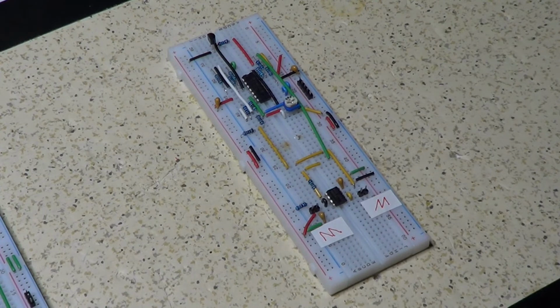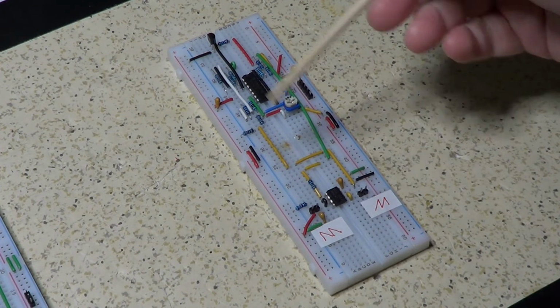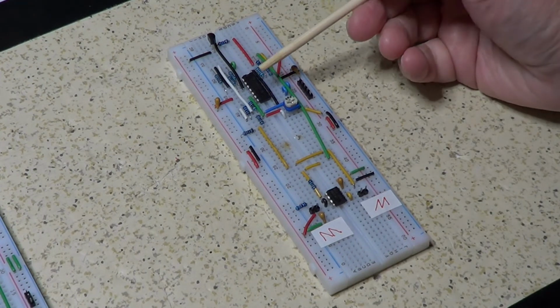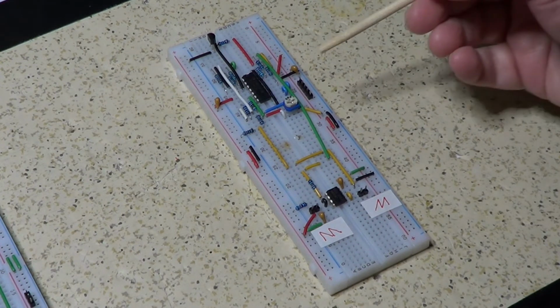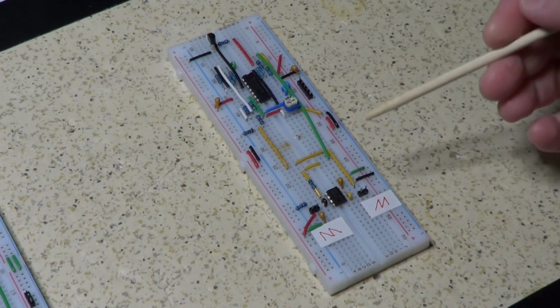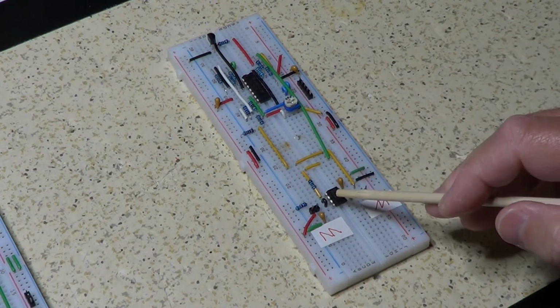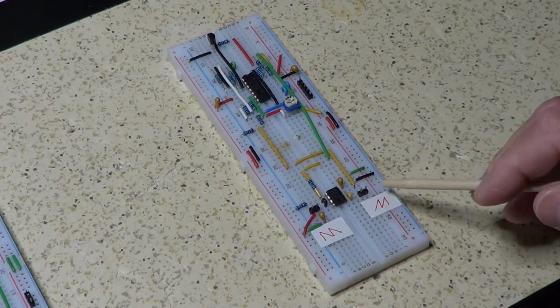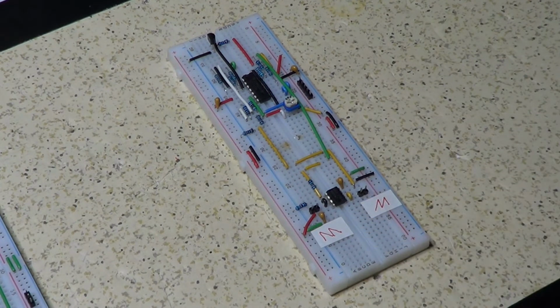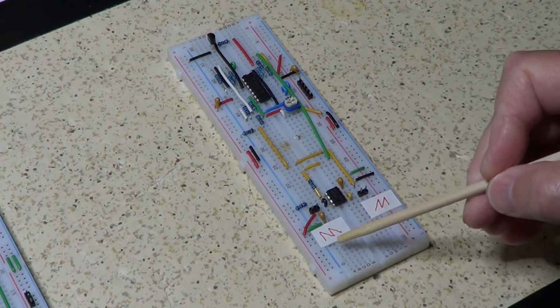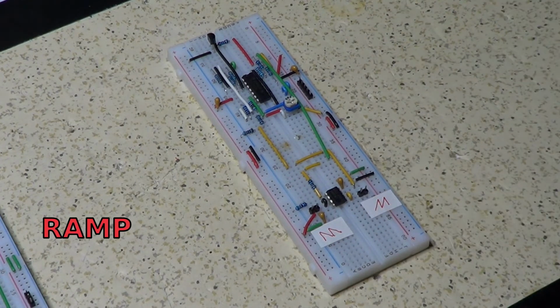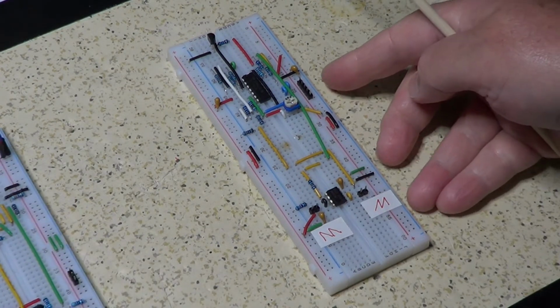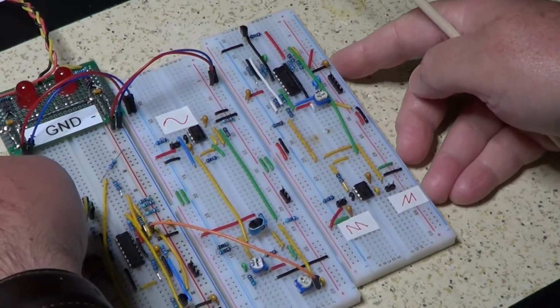And here again is the implementation of the schematic on a breadboard. Here we have the TL074 with its 4 op-amps, the control here, and we have the LM358 which provides the buffering and the impedance adjustment for the two outputs, the sawtooth and the triangular wave. Let's see how this works, so let's connect it to the rest of the circuitry. So let's put all together now.